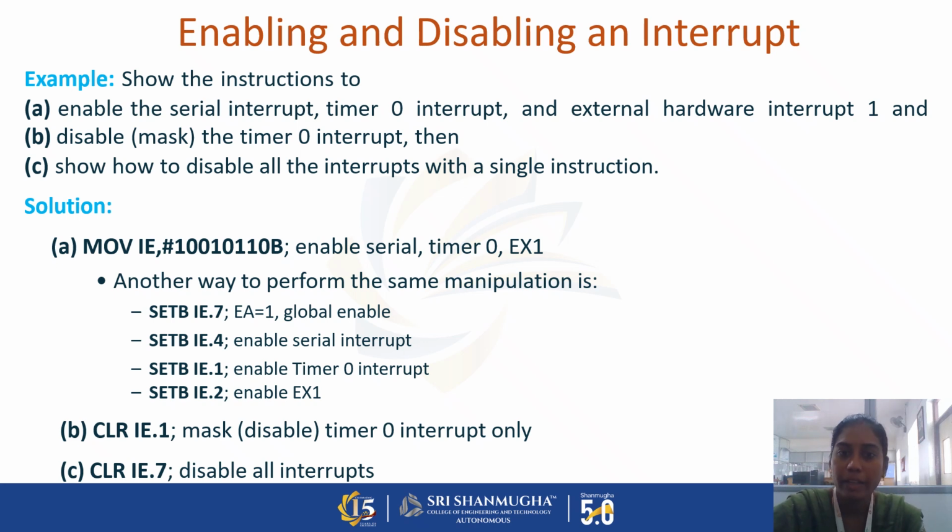So how can we disable or enable an interrupt? In this slide, we have an example. SETB is used to enable, and CLR is used to disable the interrupt.